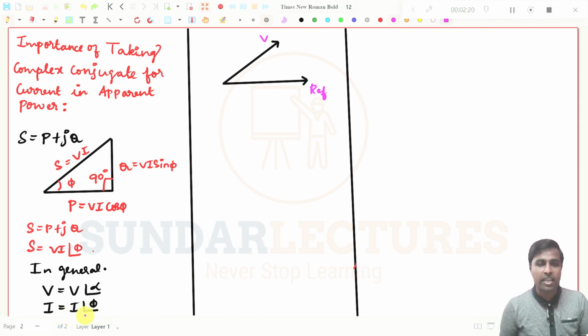And this is I at an angle of phi. If this I lags the V by some angle, we can easily say that is an inductive circuit. Let us consider this to be an inductive circuit. It will also be applicable to capacitive circuits, this complex conjugate concept, right?